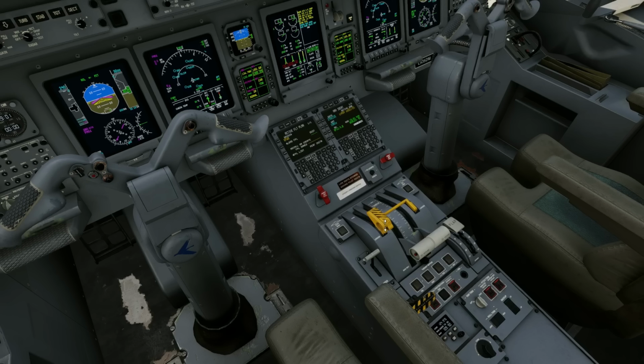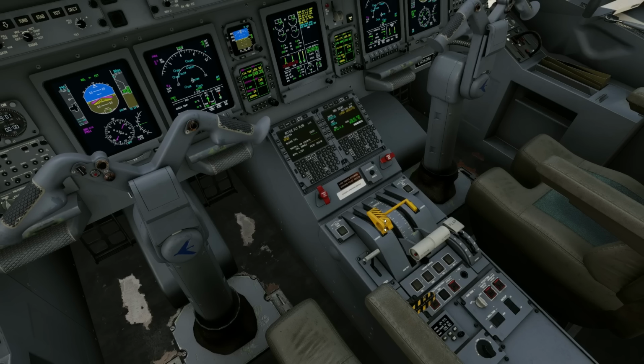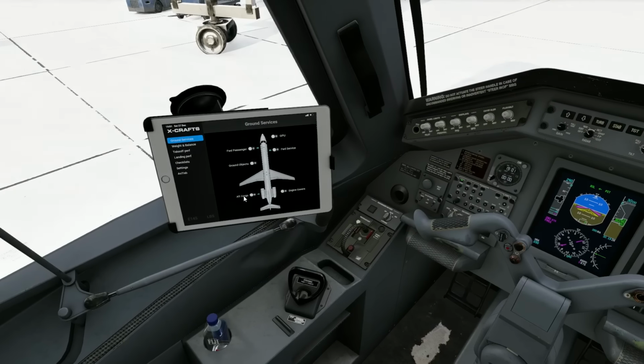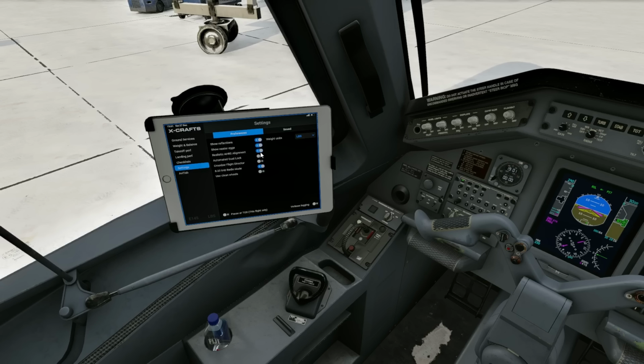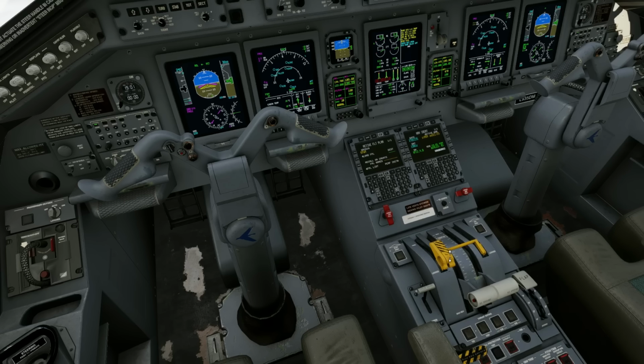The ailerons are free, so they can move, but remember with the hydraulics off, they're very heavy. To release the Gust Lock, we also have included an automatic mode. One of the new settings is an automated Gust Lock. So with the automated Gust Lock, you can release it in one click and have it completely go through its release sequence and release the Gust Lock. I prefer to do it the manual way just to show you how that works.